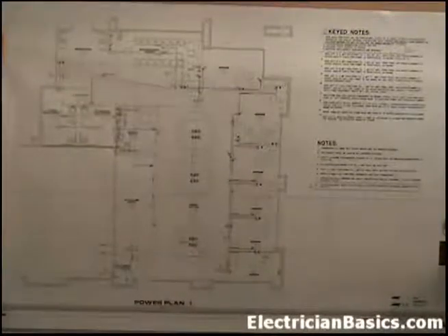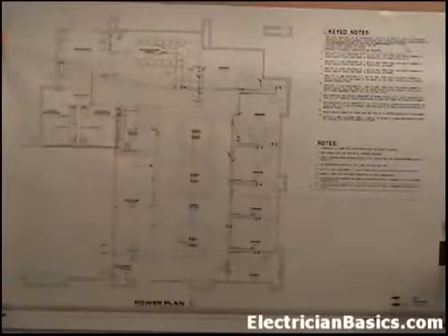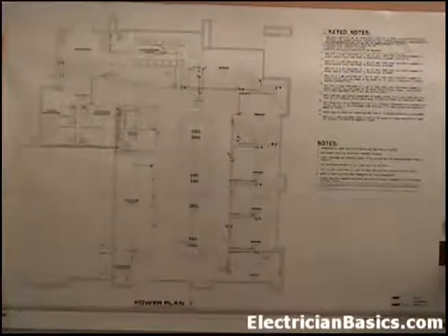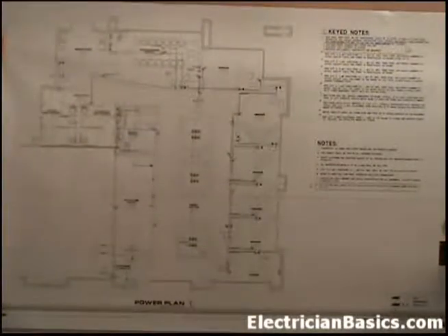Note 22 says, upon completion of the project, all changes shall be documented, and red-lined as-built drawings shall be turned over to the owner by the contractor. A red line drawing, also called an as-built drawing, shows the project as it is built. The architect will draw this out, but they don't specify exactly the runs or paths you need to take for your conduit, or where every junction box is going to be. Sometimes circuits get added too, so we need to make notification of those. This is what the red line drawings do.